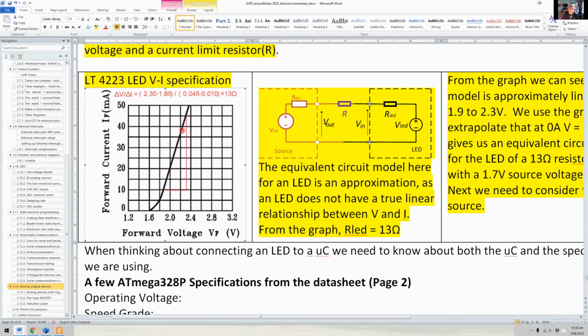You won't find that every LED is exactly the same, even as it comes off the production line. There are subtle differences in them. It's a bit like resistors. When you buy a resistor, it isn't exactly 10 ohms, but 10 plus or minus some percentage. We typically buy 1% resistors nowadays, so a resistor will be plus or minus 1%.